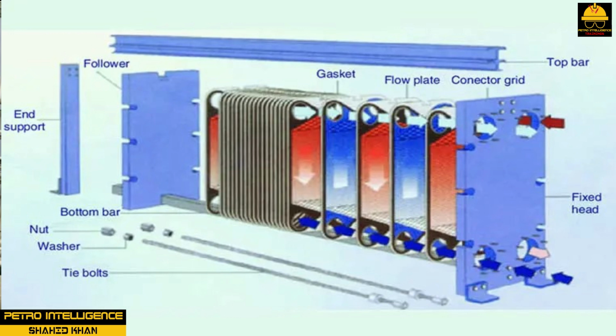It provides excellent high heat transfer. Plate and frame heat exchangers are compact and easy to clean. Operating limits of 350 degrees Fahrenheit to 500 degrees Fahrenheit, or 176.66 degrees Celsius to 260 degrees Celsius, are designed to protect the internal gasket. Because of the design specification, plate and frame heat exchangers are not suited for boiling and condensing. Most industrial processes use this design in liquid-liquid service.